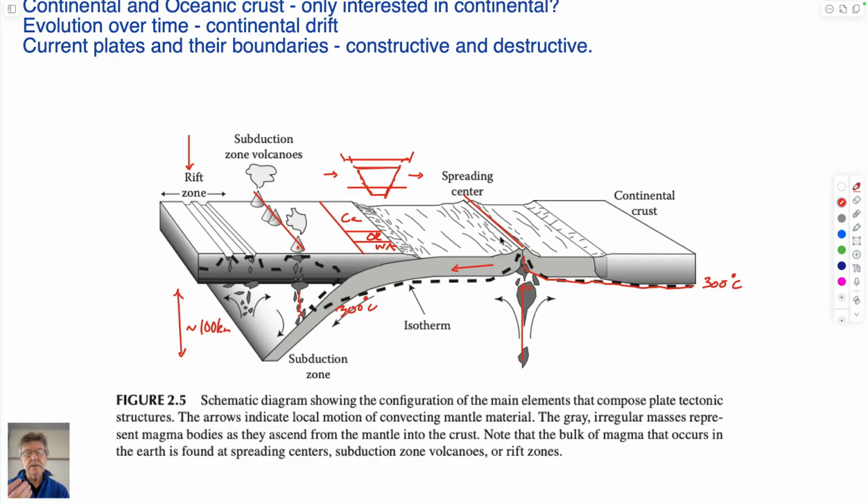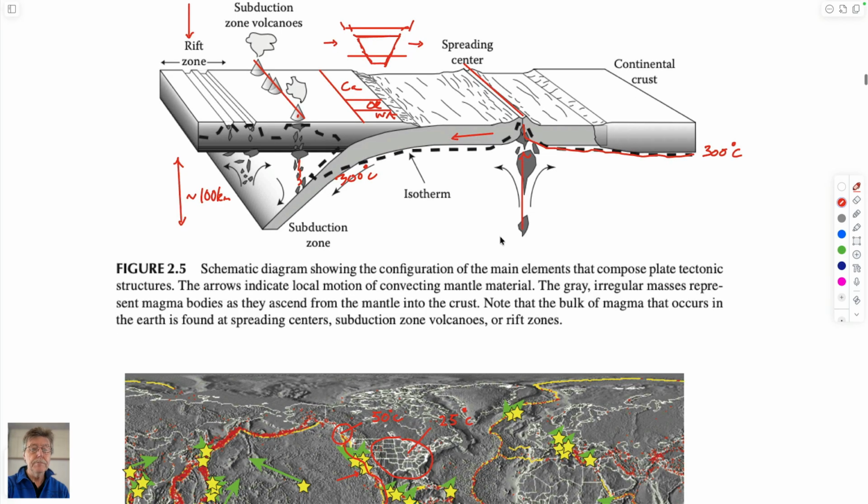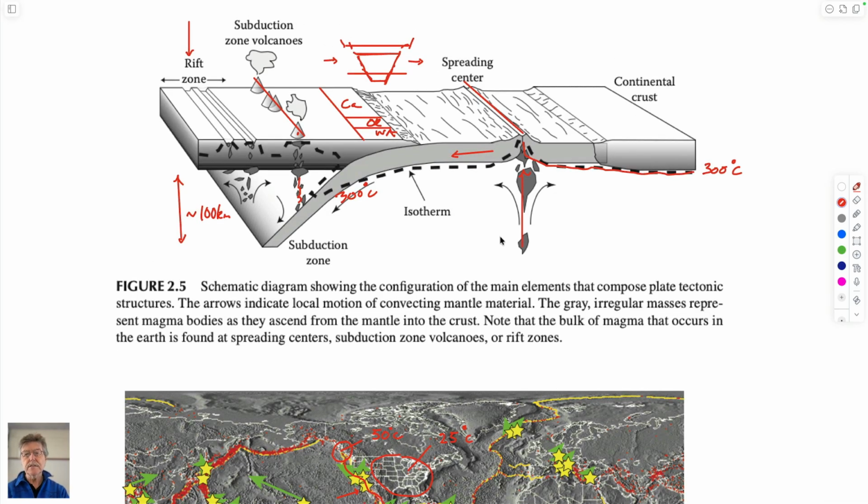And since water is the agent by which we can bring heat out, that's an important component, because we made the case that the heat rate that we have out of the system is a function of volumetric flow rate, density, and specific heat capacity, and the change in temperature as you go down depth.